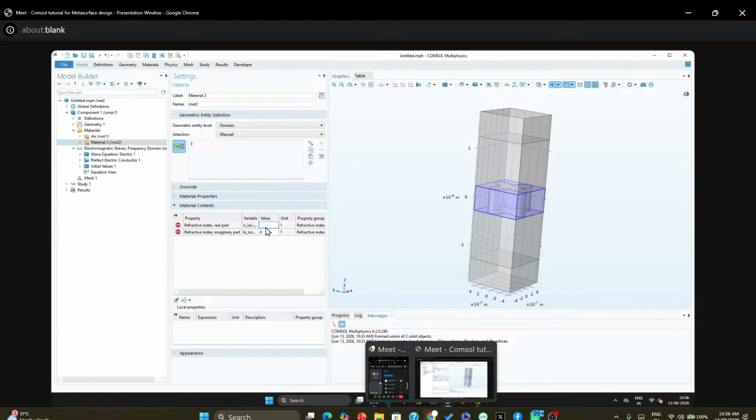And if you give here some value, sqrt of 12, I am taking silicon, so I have put the square root of 12 as the refractive index. Okay, this is the refractive index I choose because this is a constant value I chose in the paper as well. But if you want to choose some other materials, you can choose that from here.